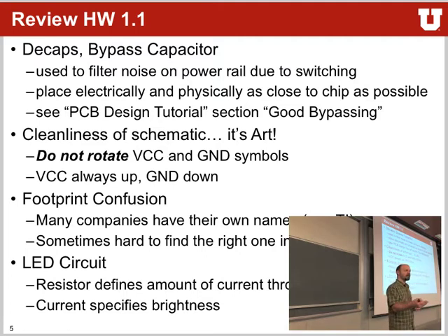But on the PCB itself, in reality, you really want them as close to the power pins as possible. So not a long line in between your bypass capacitor and your microcontroller, because that's an inductor again. So you have an introduced problem. So you want these bypass capacitors as close to your power lines. There is a document online on the website called the PCB design tutorial. There is a very good section in there called good bypassing. So have a look at this section, or actually at the whole document, because it's a really good read.